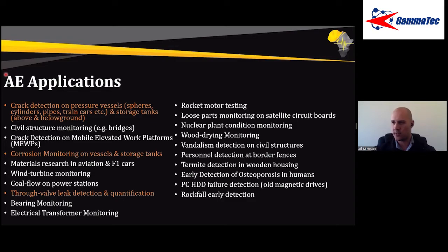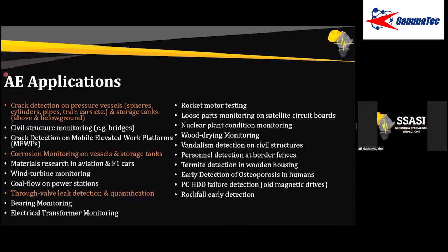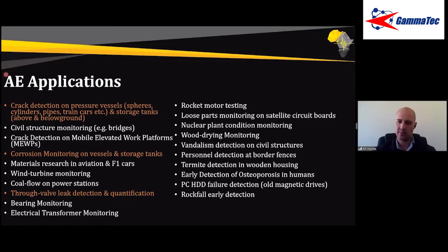Same thing in structures, where if your vessel has seen a certain load and pressure in service, if you apply the same load or slightly below, you most probably won't hear the acoustic emission. But if you go slightly higher, in practice we go 5 to 10% higher than previous maximum, we are able to detect and locate the defects there.